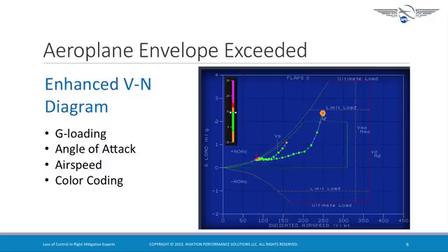So it gives the instructor a really good understanding of the airplane with respect to the load limits of the airplane, the airspeed limits of the airplane, the angle of attack or margin of safety during the recovery, and then the combination of the maneuver to see how these parameters change to a point where there may be a debriefing topic. So in this particular case, because the airplane's flight attitude was so high, a debriefing point in this situation may be that because of this particular configuration, because of this particular situation or condition, unloading even more than the 0.5 or 0.4 G loading may have been merited or required to maintain more of a margin of safety. So in this particular maneuver, the pilot perhaps should have unloaded to a 0.1 or 0.2 G limit. And remember, we always want to stay at positive G in airplane upset. And the reason why is to maintain a margin of safety away from the critical angle of attack. So very, very informative, this diagram.